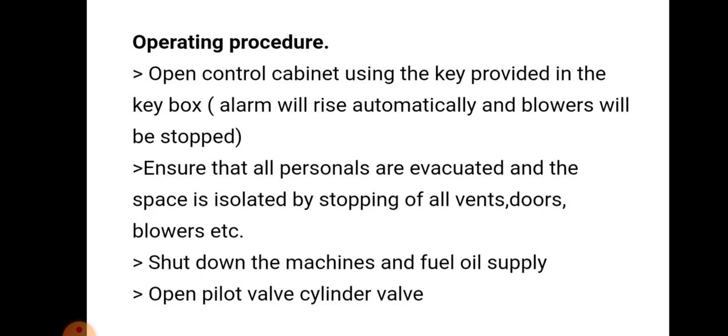Alarm will raise automatically and blower will be stopped. Ensure that all personnel are evacuated and space is isolated by stopping of all vents, doors, blower, etc. Shut down machines and fuel supply.